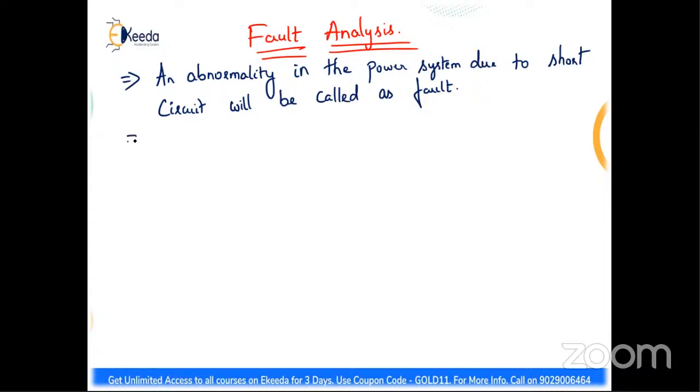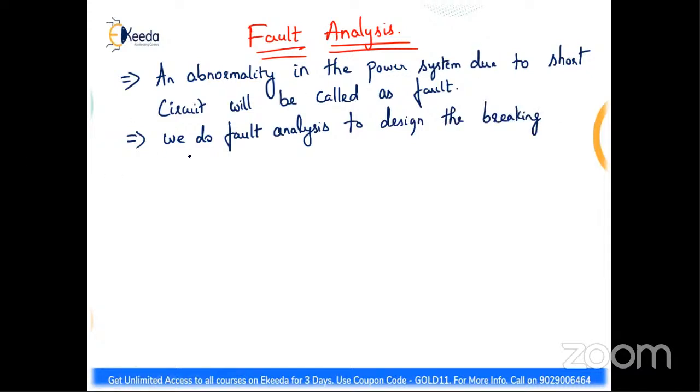So what we should do is the fault analysis, right? How are we going to do the fault analysis? We do fault analysis to design the breaking capacity of a circuit breaker. This is a very important point.